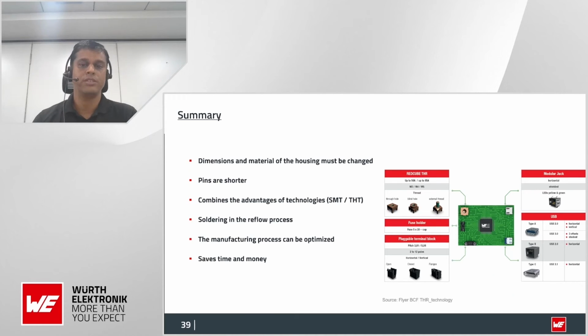Soldering in the reflow process and the manufacturing process can also be optimized, because the SMD components and through hole components can be soldered with the reflow process. By doing so, we can save time and money. So this is about the THR process.